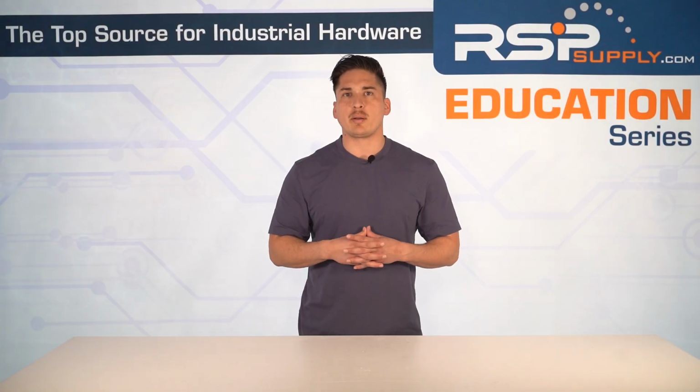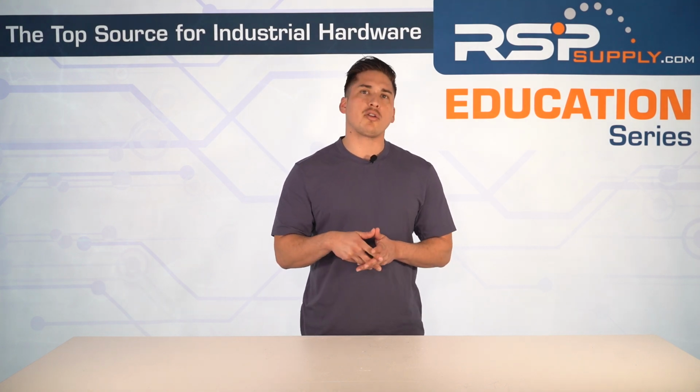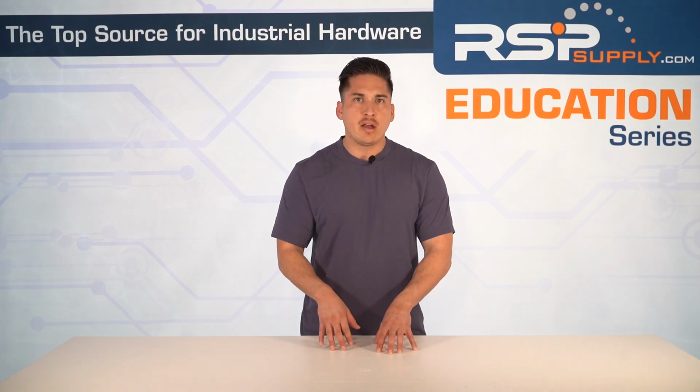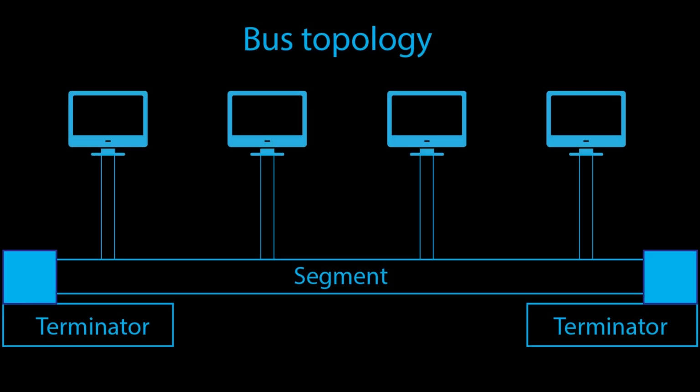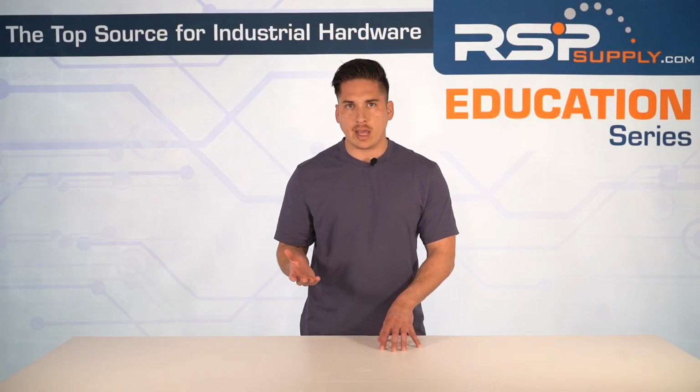Field bus networks like Profibus or DeviceNet were the standard before Ethernet took over. They are slower, but they're extremely reliable in harsh and hazardous environments. Field bus is typically going to use a bus topology where devices are connected in a series along a single communication line. This simplifies wiring and it can reduce installation cost, but it does make the network a bit more vulnerable if there's a break in the cable.